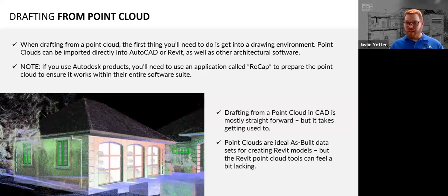Drafting from a point cloud in CAD is pretty straightforward, but it does take some getting used to. There are lots of options in CAD to color, slice, crop, move, and rotate the cloud in different ways. And you'll need to use the view cube to regularly adjust your UCS orientation properly to work with the cloud in different positions.